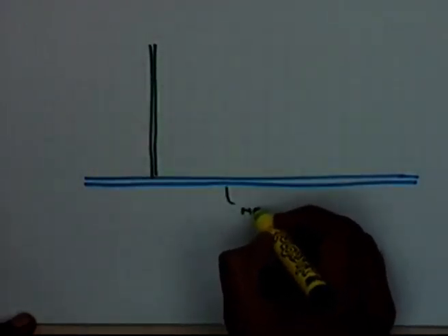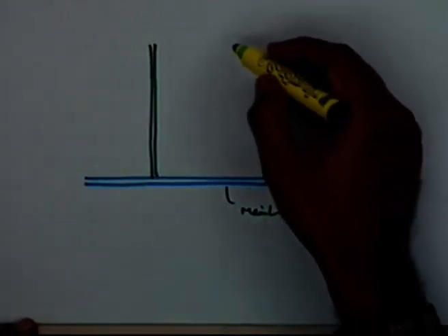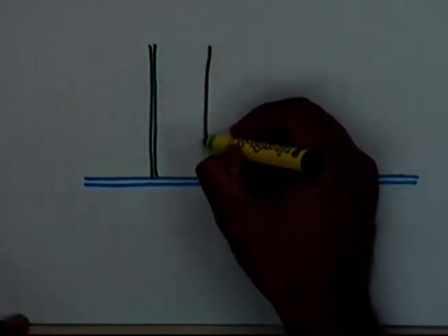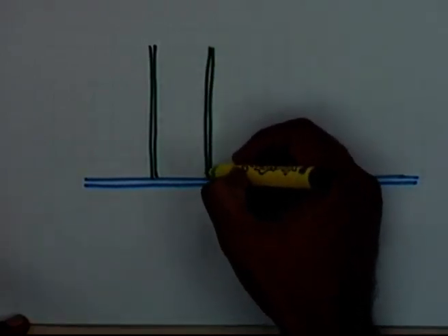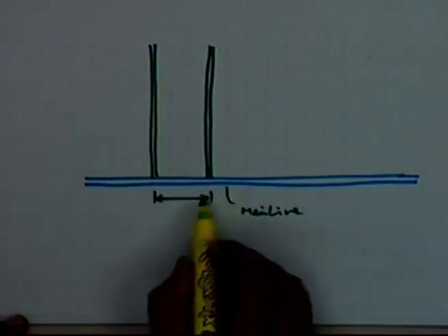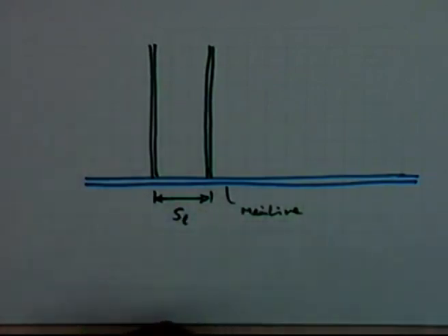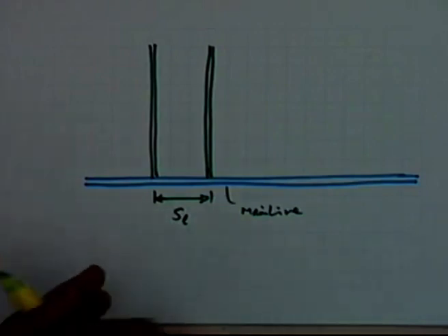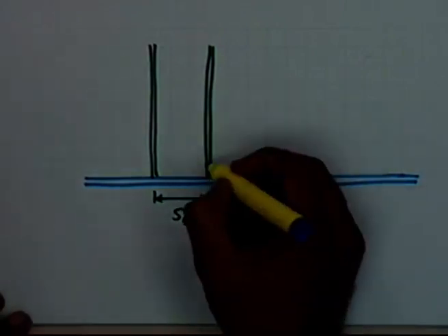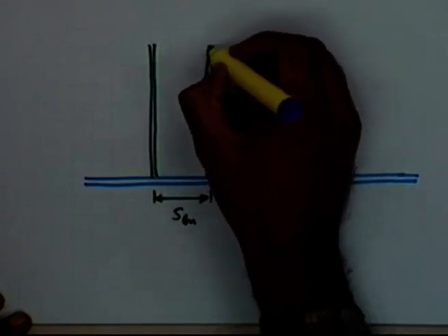This is the main line, and the overlap will be because of the two spacings which we have considered. One is the spacing between the laterals, which we were calling the mainline spacing, and on the lateral you have these individual sprinkler heads installed.